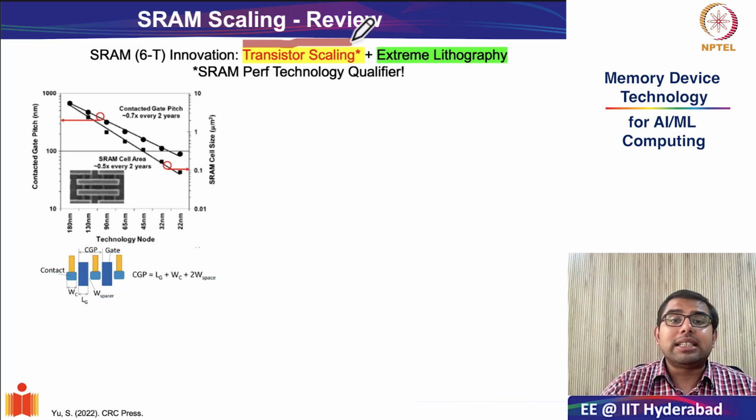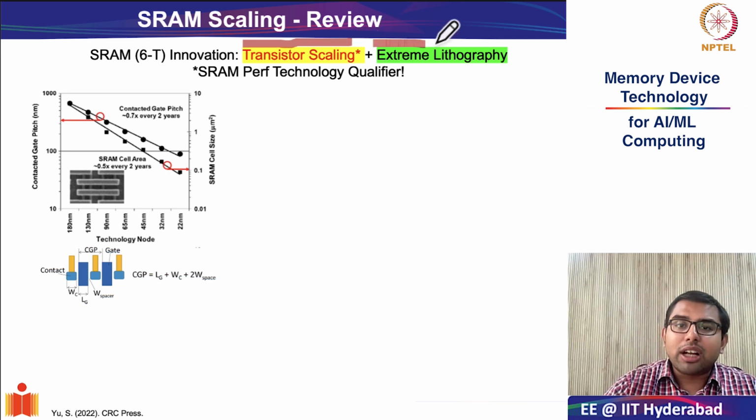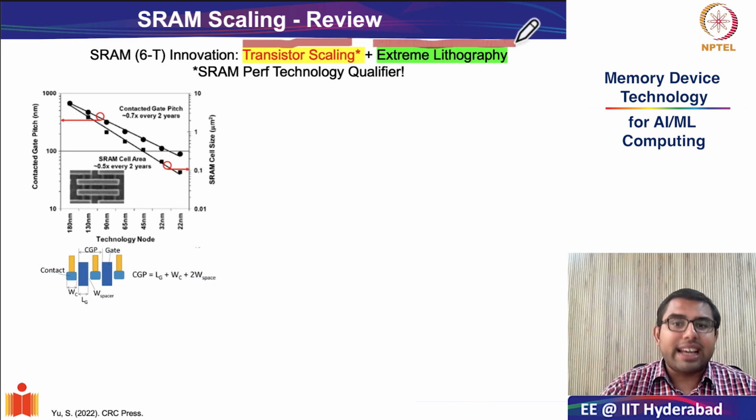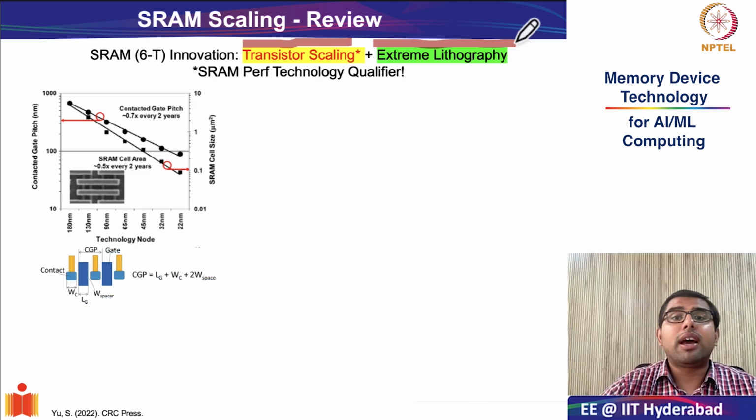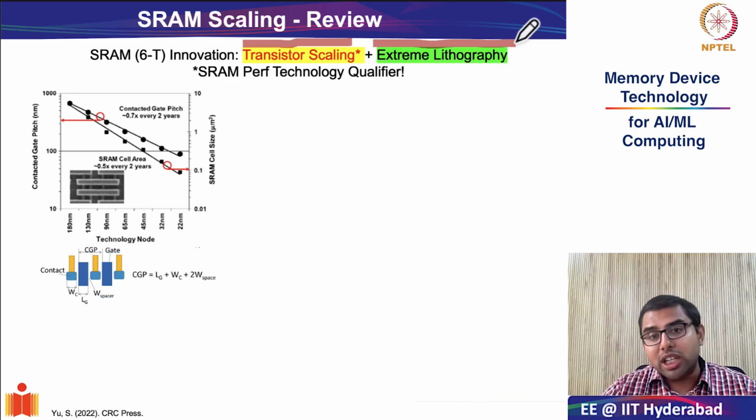Transistor scaling is the phenomenon where reducing the channel dimensions of the transistor or the form factor of the transistor gives you multifold benefits in terms of area scalability, cost, power consumption, speed, etc. And anybody who has done a basic course on VLSI technology or CMOS processing technology will know that transistor scaling has been only enabled through extreme lithography.